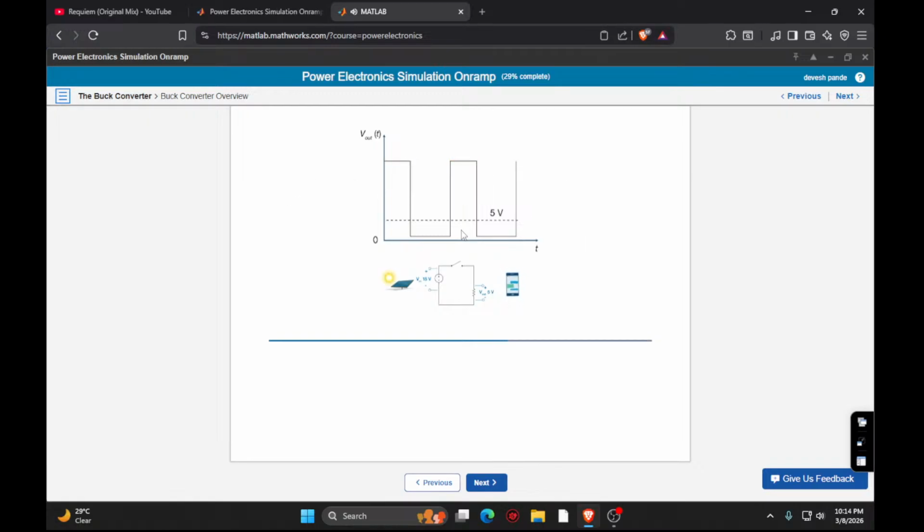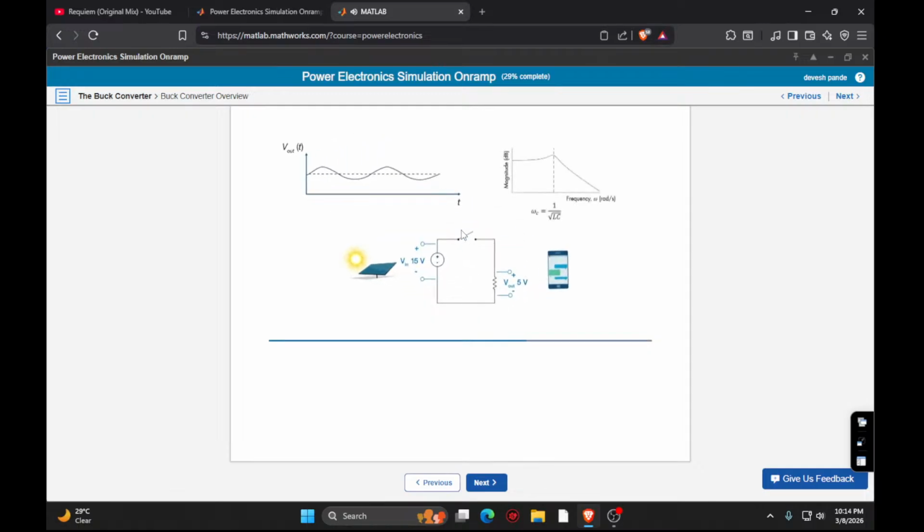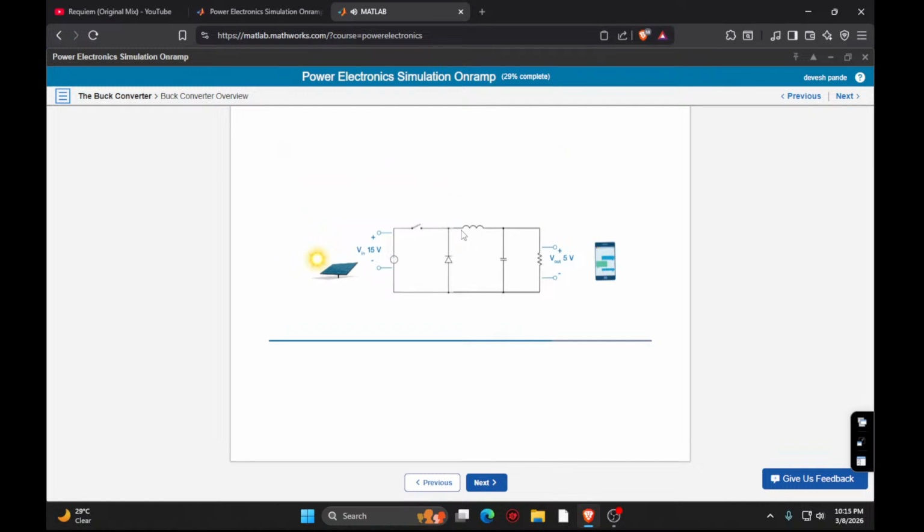What we need now is something to smooth the high frequency pulses into something that looks close to a constant DC value. Something like a low pass filter. Adding an inductor and a capacitor to your circuit smooths out the high frequency switching, leaving behind a signal that's nearly DC. The complete buck converter circuit also includes a diode, so current can continue to flow while the switch is open. The relationship between input and output voltage, switching frequency, and component sizes all factor into the design of the buck converter. The simulation lets you quickly iterate through designs without ruining your phone.